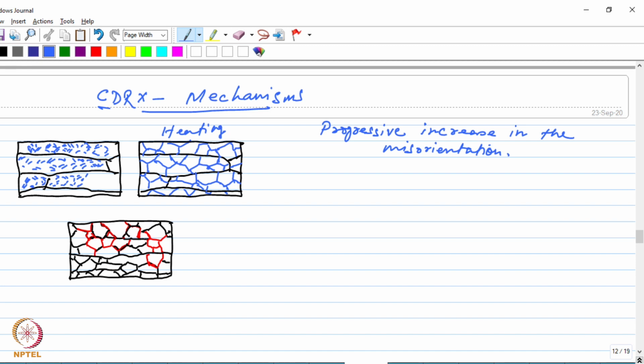So when you have heat being applied simultaneously, contrary to this kind of cold worked structure that you might have when the material is deformed at cold conditions or at temperatures below the recrystallization temperature, you will have this kind of well developed dislocation substructures with these low angle sub-boundaries formed by the dislocation rearrangement. And that's the dynamic recovery process, as I said.